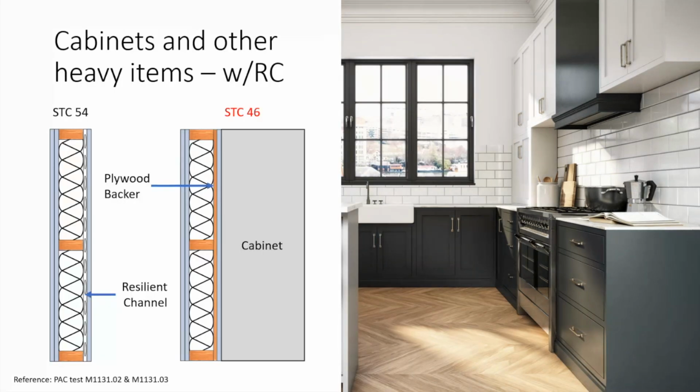So if you do this, you have your base wall here on the left, right? It's an STC 54 from this acoustical test series. We've got resilient channel, a few layers of drywall. If we do the standard detail that I saw a lot consulting, you just put in 1/2 inch plywood or OSB shims and then screw it all together. You reduce your STC rating by 8 points. You go from a 54 to a 46. So you go from comfortably above multifamily code minimum to well below that code minimum.